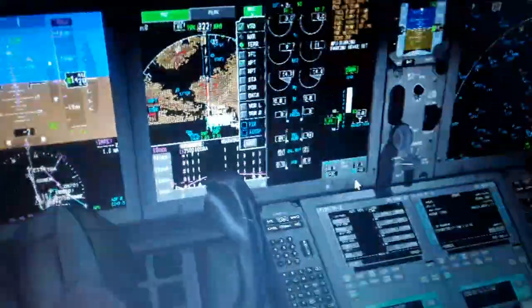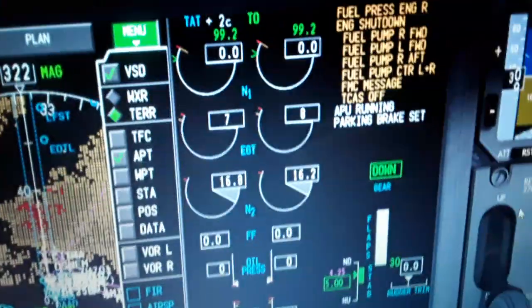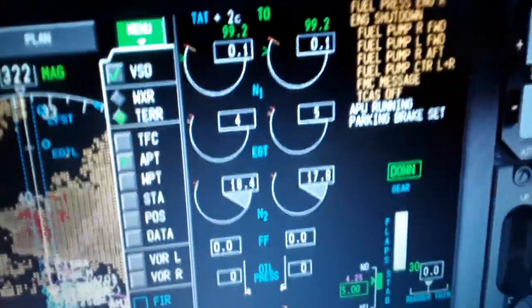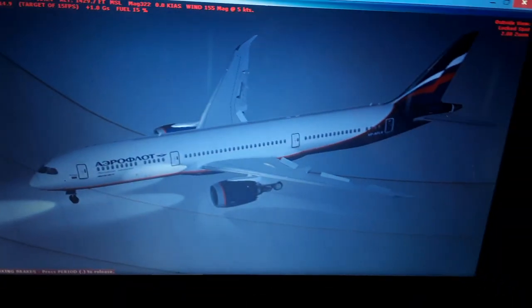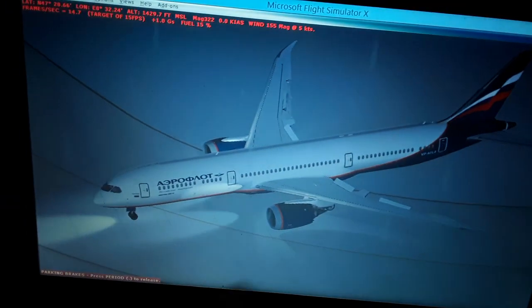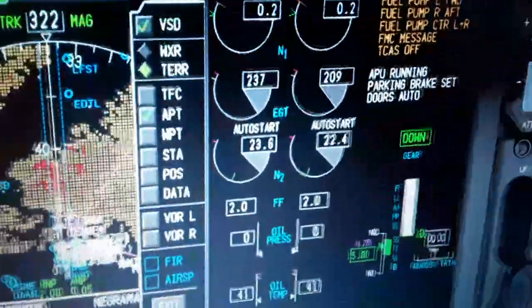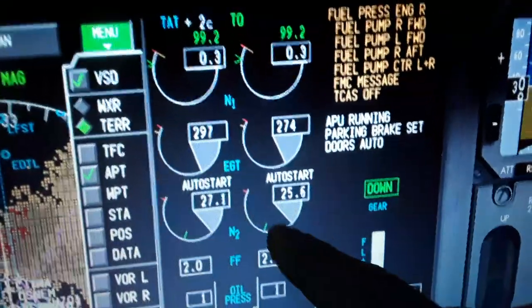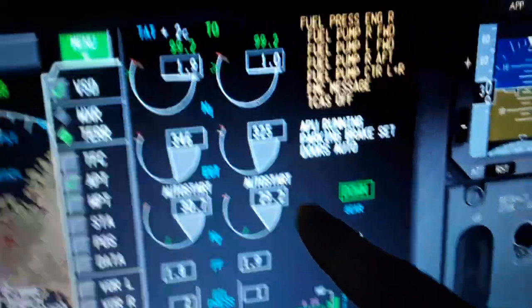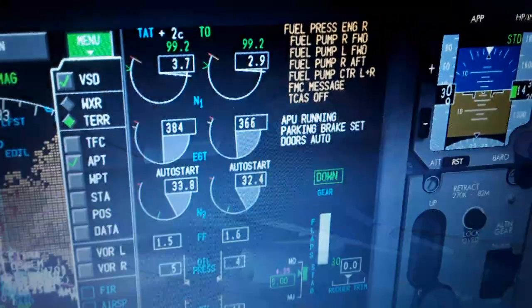You will see the pressure from the APU is increasing, only pressure right now. So you can hear also the roar of the engines. We have pressure right now, but no fuel. So we let the fuel flow on. Fuel control over here, left and right engine running. So the auto start will kick in, will turn on above 30%, will turn on the fuel control.